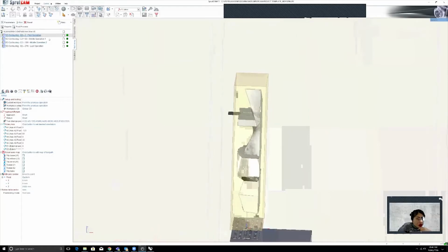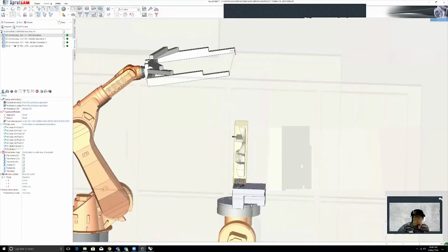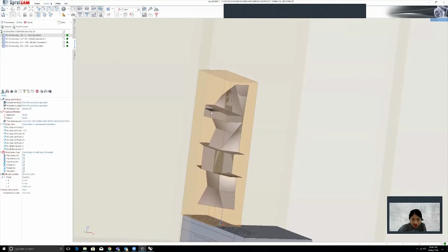The first thing we're going to do is have it at E2 equals 0, E2 being the actual table, and 0 being the actual angle of the table. So 0 means that the rotation of the table is at 0 and it's facing the robot. And because our assist geometry is conveniently placed there, we're going to use E2 equals 0.